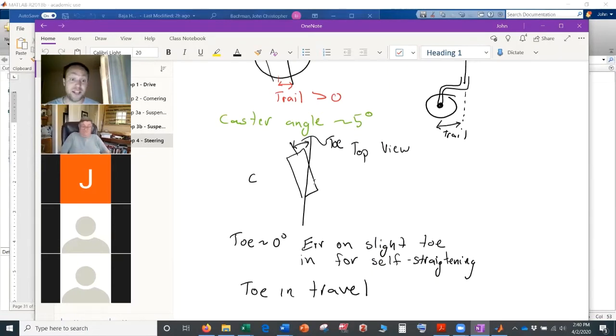right? So that, for example, as the tire goes up, like think about making a right-hand turn, as that weight gets shifted to the back left, there's been arguments to have that back wheel as it travels up toe out to kind of kick you around the turn. I mean, I'm still skeptical about how much turning is ever done by the back wheels on our Baja cars these days. Maybe in the past they used to have kind of wider in the rear, but these days we totally drift out that rear on tight turns, basically.